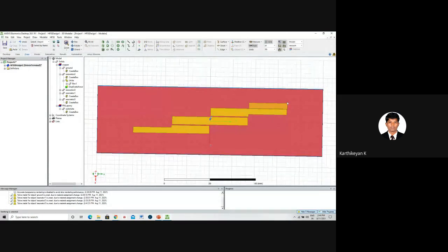So you are going to create another resonator that will touch this end. If it is touching this end, the end of the substrate, you can give the input at this side. On the opposite side, this end, we are again going to duplicate the same resonator. It will touch here. This will be port 2. So this is a 2-port device.